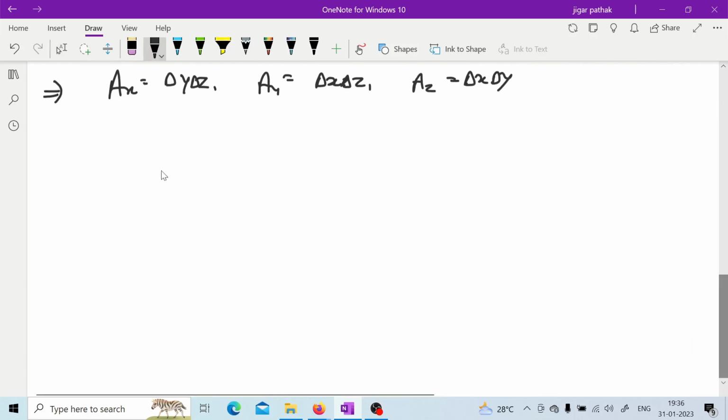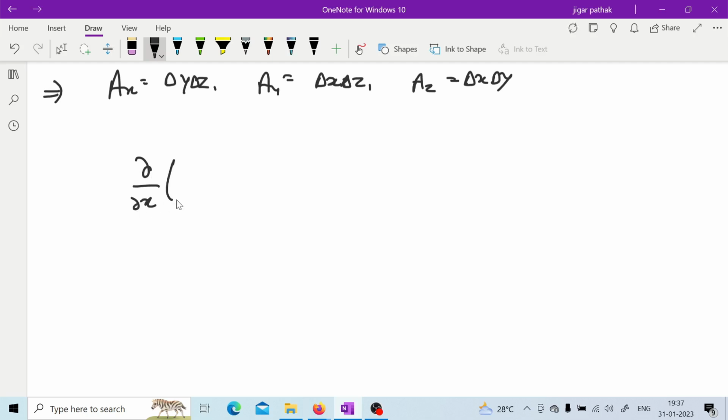So for this you have all these areas. If you consider all these areas, and put all the above values in that equation, and consider that qx plus delta x minus qx over delta x is nothing but kA delta T by delta x, which we considered while doing 1D heat conduction. I am skipping some of the steps and directly writing. You will get something like this if you put all those values and simplify. Then you will have this equation.